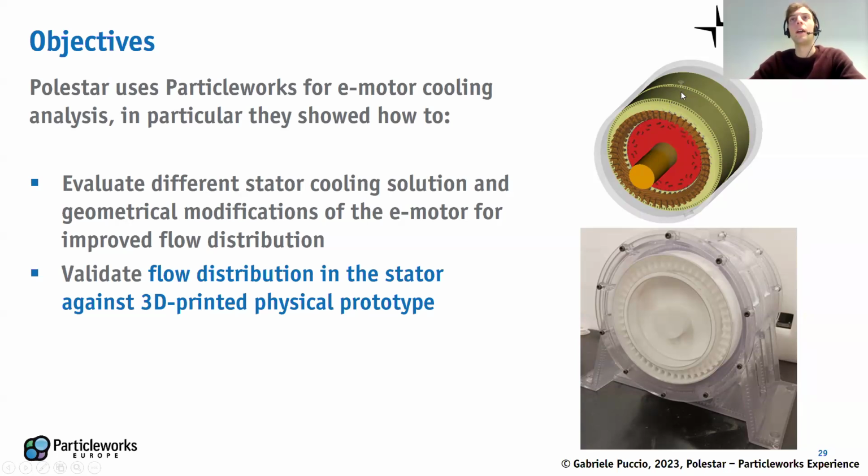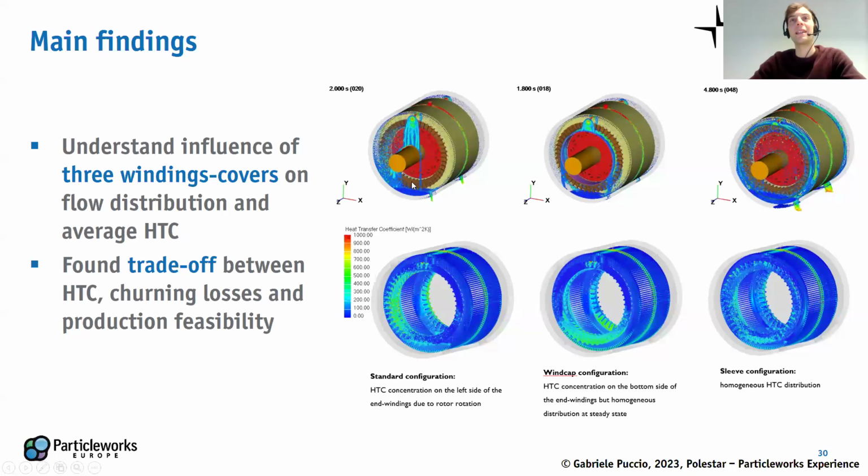So it's like a coupled stator to windings cooling. One objective was to understand if the transient flow, when we start to inject oil there, could be captured as compared to a clear casing. But the other objective of this study was also to analyze the possibility of changing the sprayed oil around the winding. Here you see 3 configurations.